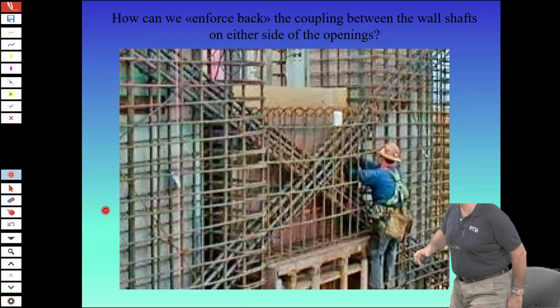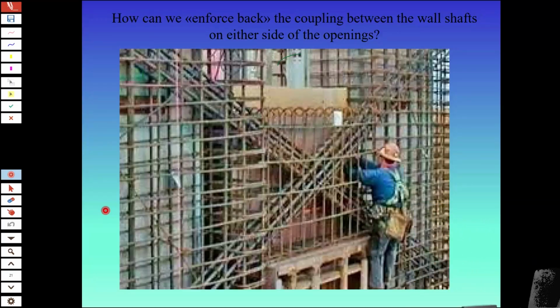that you have a very high congestion because, you see here, you have a bundle of diagonal reinforcement, because you have to put it on either side of the wall. A wall is 20 centimeters thick, so you have to put it on both faces. And here it's not very clear, but you also have to tie this diagonal reinforcement with stirrups.